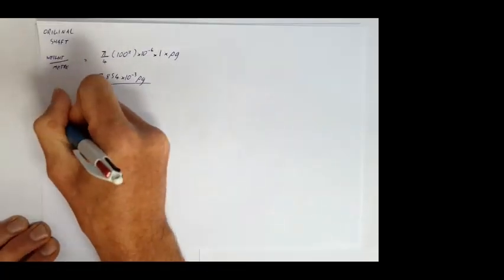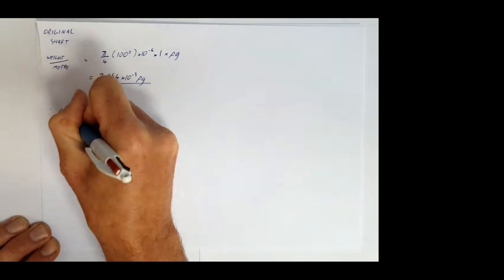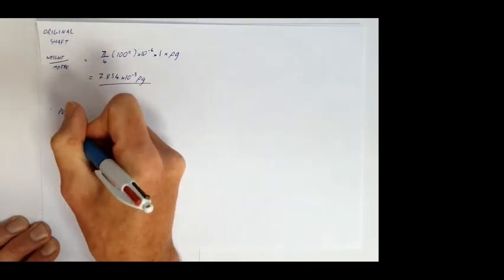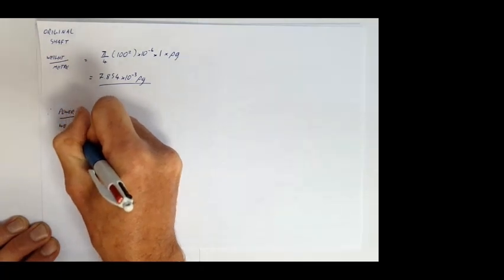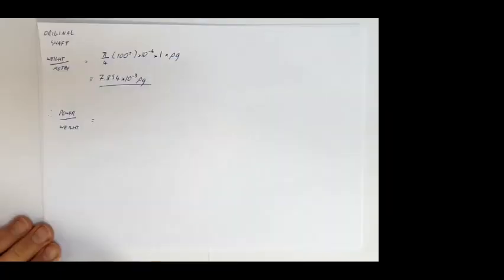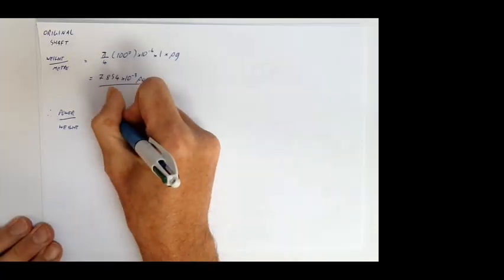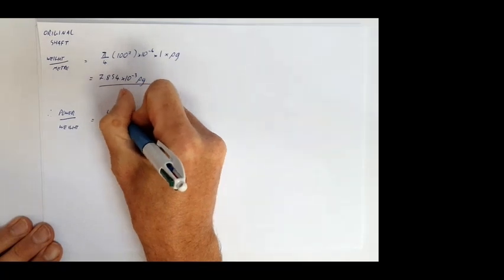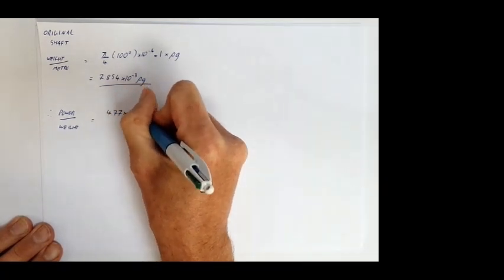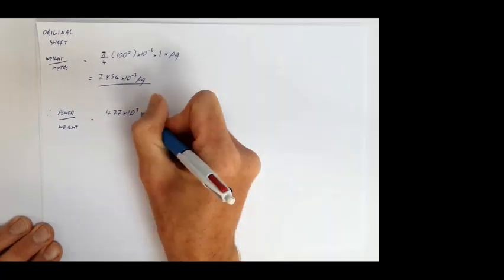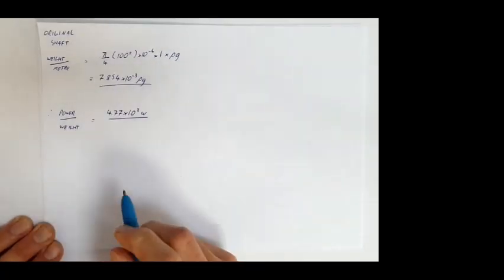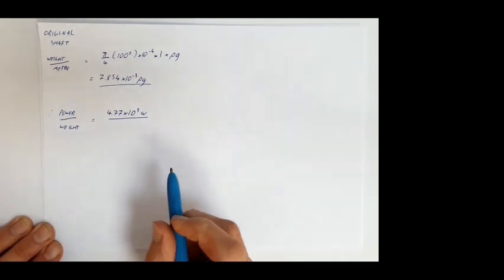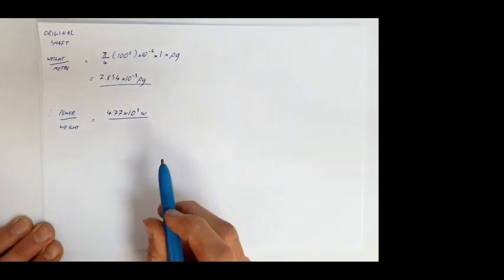So therefore, the power to weight ratio for 1 meter is going to be, okay, so the power is the torque times the angular speed. So that's 4.77 times 10 to the 3, the torque that we were transmitting, times omega, which gives us the power. In the first part of the question, that was actually 75 kilowatts, wasn't it?